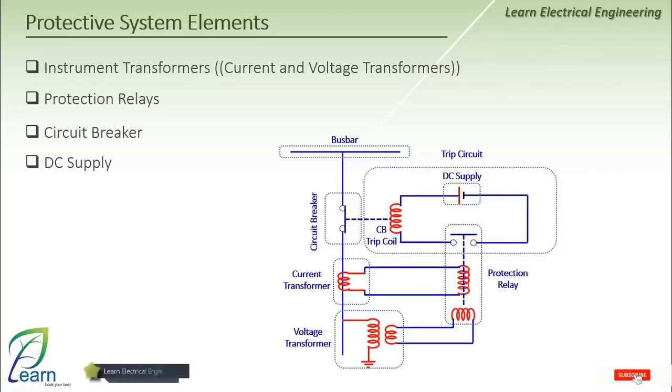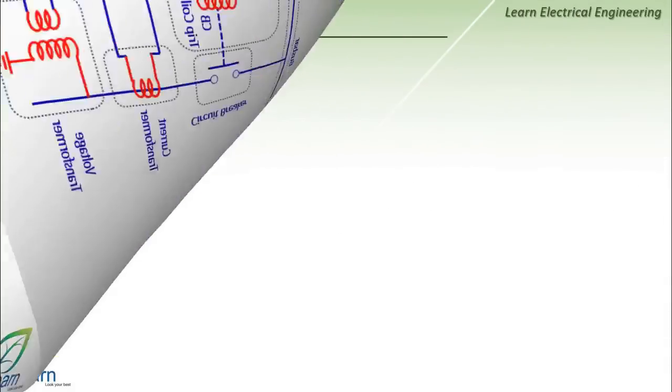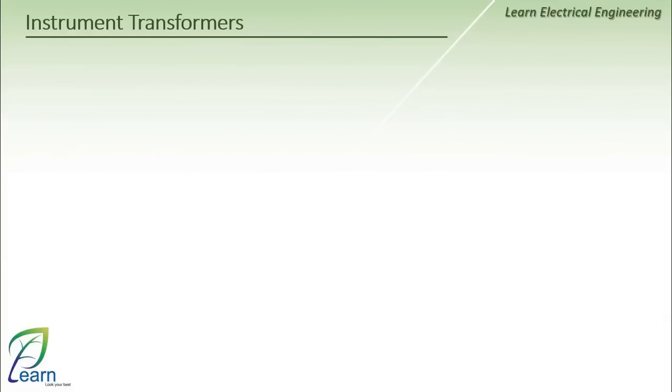Assume that the circuit breaker is closed and at some moment there is a fault on the feeder bus bar, which will be the source that starts supplying the fault. So how does the protection system work? The CT and VT will start supplying the values of the current and voltage, and based on the settings inside the relay, it will be able to determine the fault. It will trip the circuit breaker to disconnect and isolate the fault from the rest of the healthy system. The circuit breaker opens to extinguish the arc. Once open, the current and voltage will return to normal and the protection system will receive a message and reset the trip command.